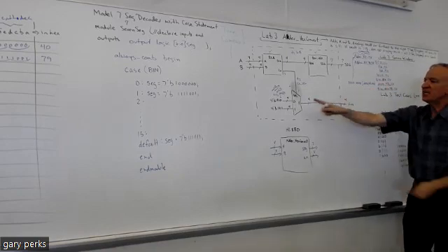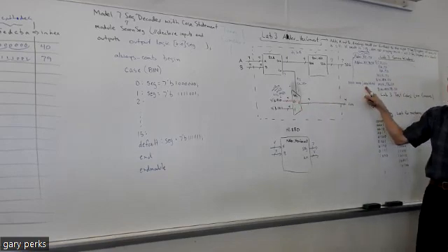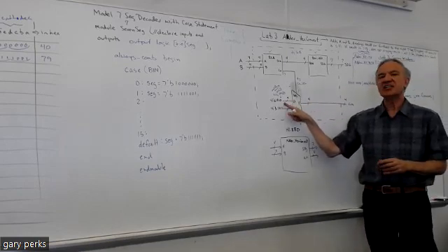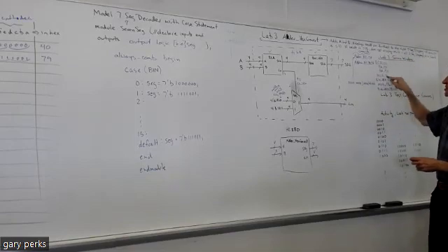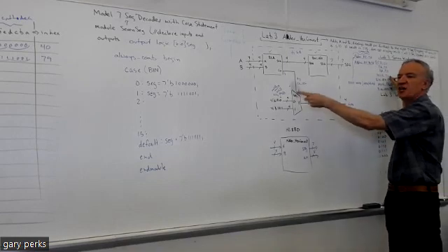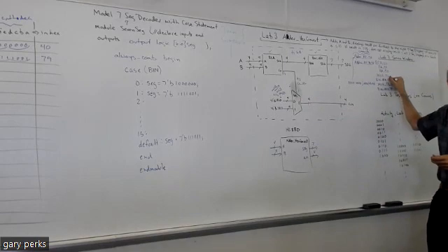So that's how you make connections to data: you put whatever input you want to connect to the data, then in the parentheses, you put the data. Now, some people make this connection in the mux module, but the reason I don't like that is because if you go to use this mux module in another design, you have to edit it.